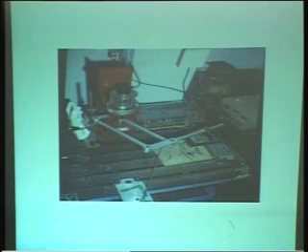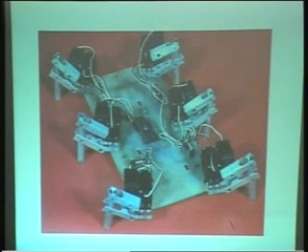The rotor is something like a PCB. I won't go into further details. It's very light, so that the motor can accelerate very fast. See, one of the important requirements in robotics is the ability to accelerate very fast. So we have used the pancake motor in this particular experiment. He was trying to build a high-speed robot. You can see the electronics beside it. Here is the same servo motor I had shown you, the same one used in the walking machine. They range from very small sizes.